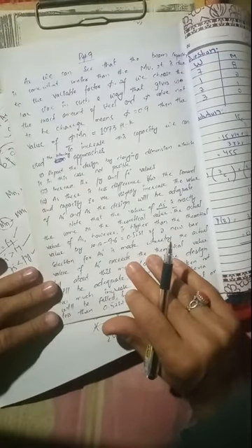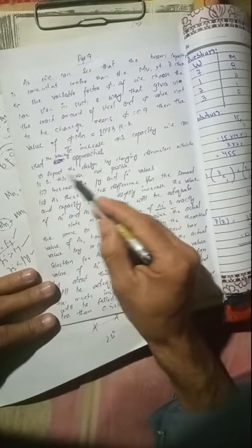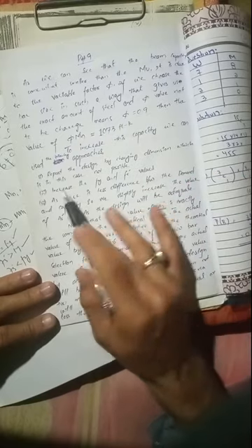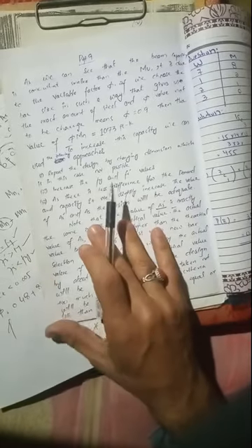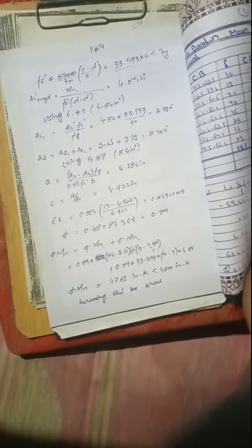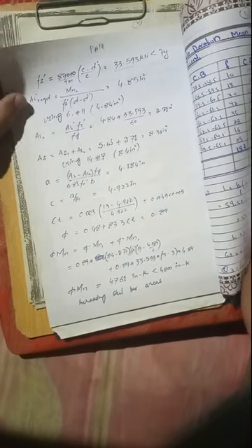We have three different options. Okay, there may be some other options. But as in example number 10.9, lecture number 3, we discussed the three possible arrangements. We can't use the first arrangement because we are bound here. We can't change the dimension. We can increase Fy and Fc prime value, and we can increase the steel reinforcement, as we did in lecture number 3 for example number 10.9.